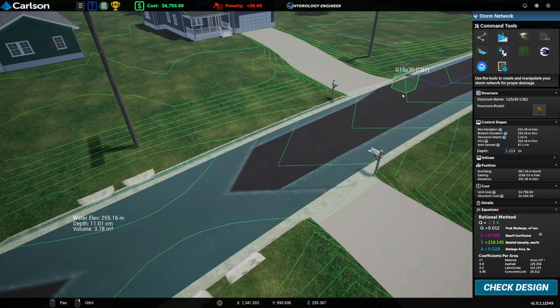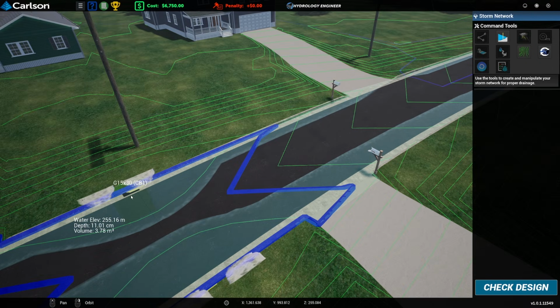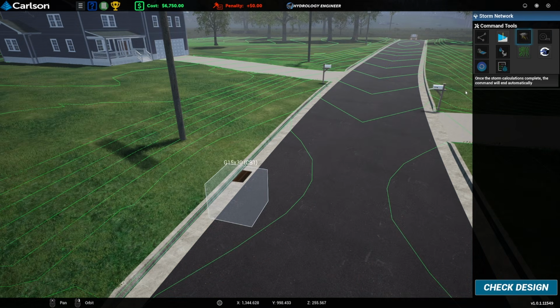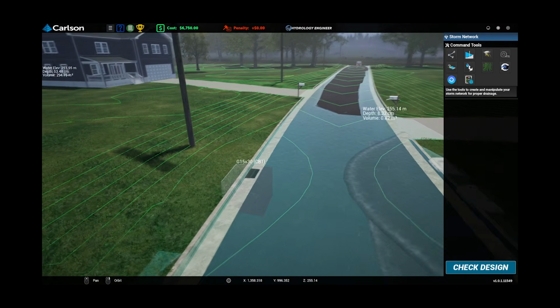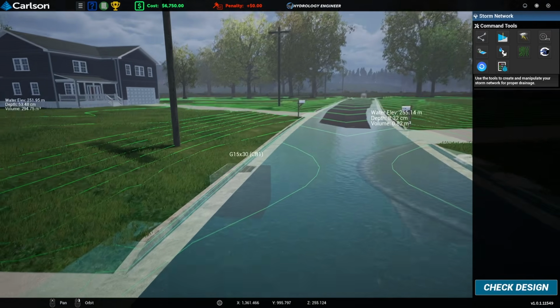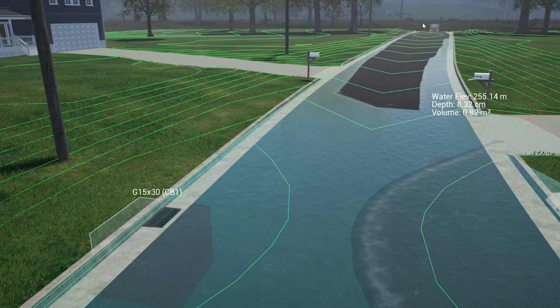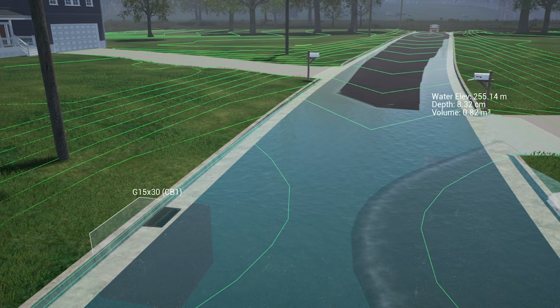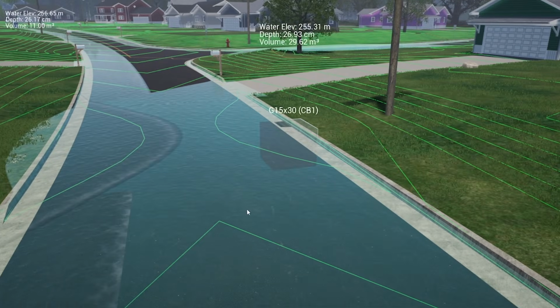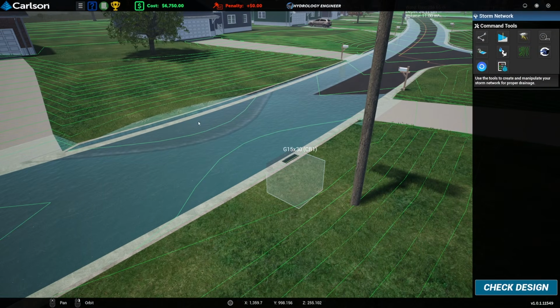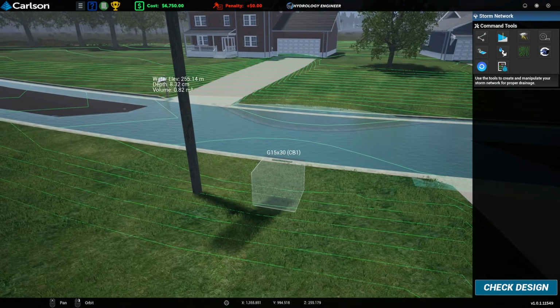Blooming out. Okay, then I'm literally wondering, if I were to put this at the low point, which is down there, what would the flow width do on this side? Let's run one more time. So, oh boy. I guess that's not too surprising, because it's important to note when you're working with low points, you can't just look up one side of the road. It's a low point, so there's going to be another side of the road that's also contributing to your side. We've also got this side of the road as well, which probably isn't helping.